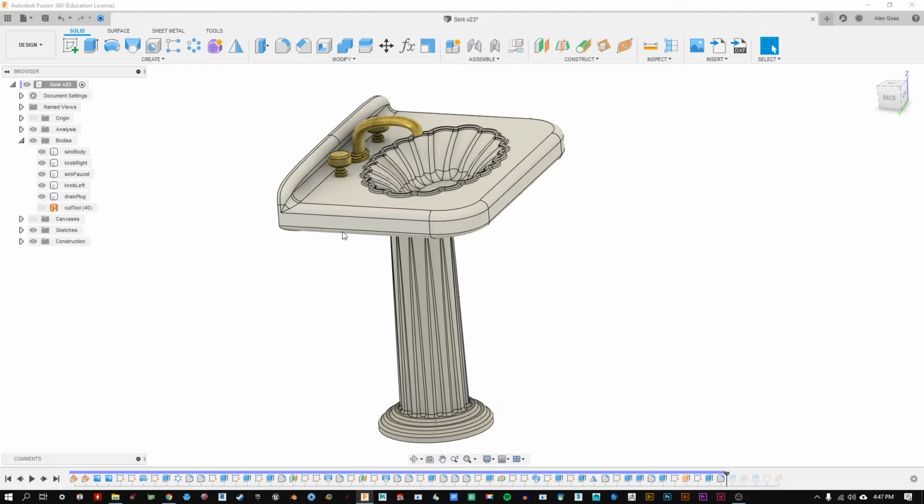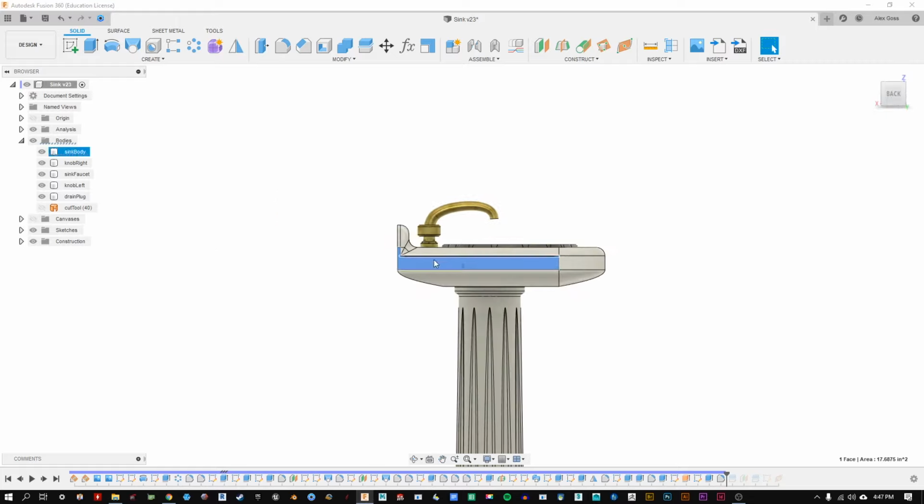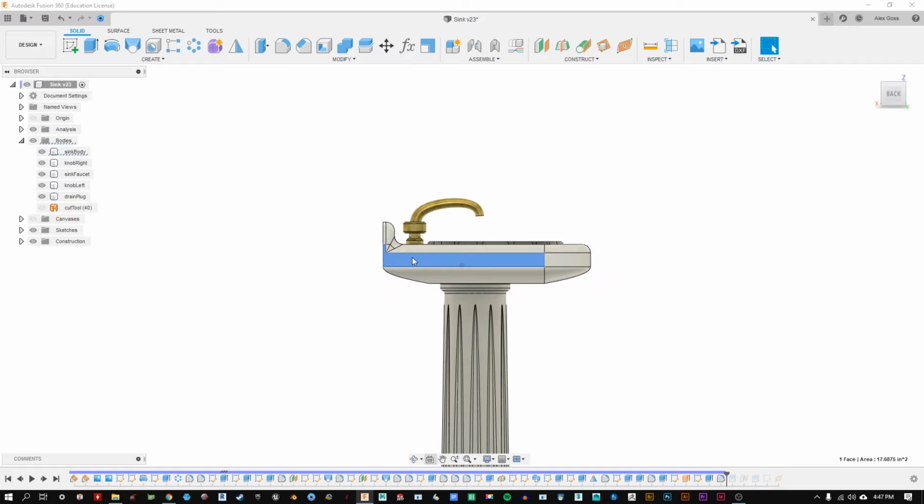But what Look At can do is if we have a flat plane in question, not a curvilinear surface, but a flat plane somewhere in our model, not those origins, but somewhere else. If we have that object or that plane selected first, and we click Look At, it will align our screen to be exactly coplanar or aligned with that surface.